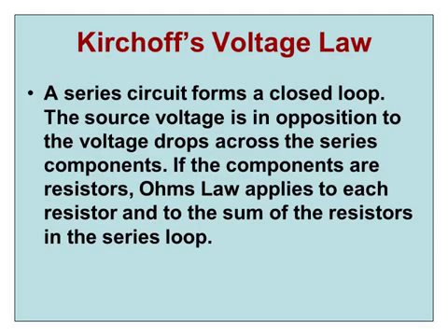A series circuit forms a closed loop. The source voltage is in opposition to the voltage drops across the series components. If the components are resistors, Ohm's law applies to each resistor and to the sum of the resistors in the series loop. This actually gives us some degree of redundancy in how we apply the equations and solve a circuit.